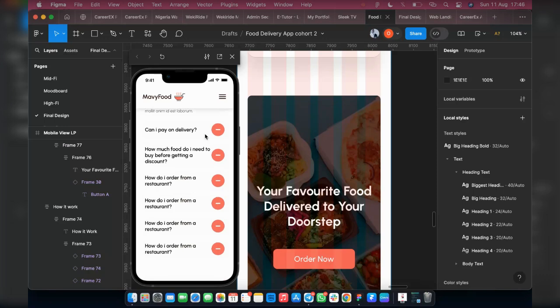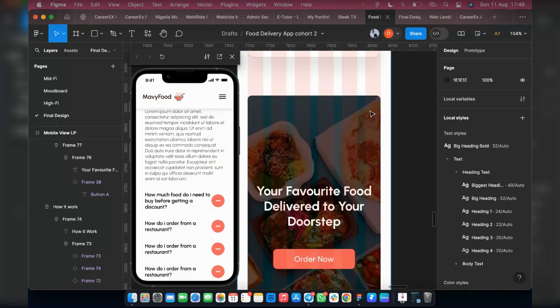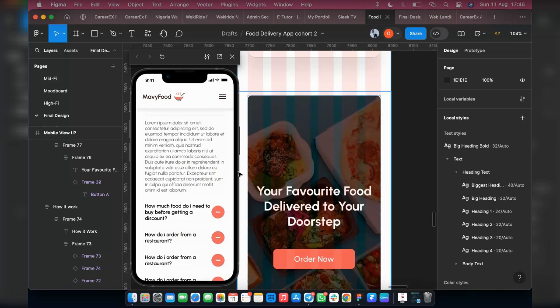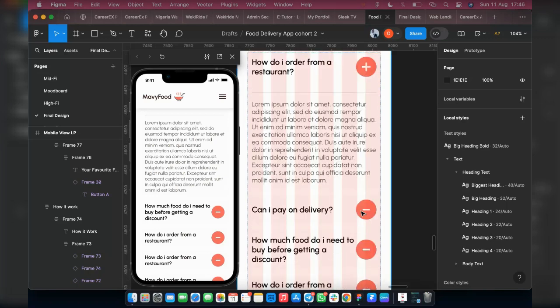So in this part now I click on it. You notice that the font text I did not reduce it. So in this aspect, what you are going to do is you're not going to touch the component. All you have to do is just on the variant that you've already designed here. So on this variant, we hide the text. You're going to click on all the text and reduce the font size. You are not going to touch the main component. Just touch the variant, reduce the font size so that it will align to what is already here.